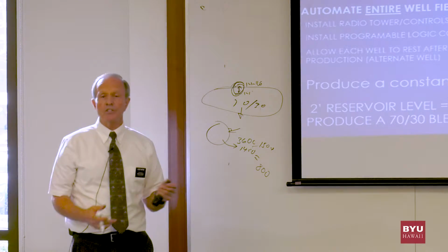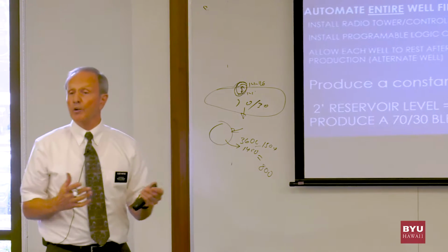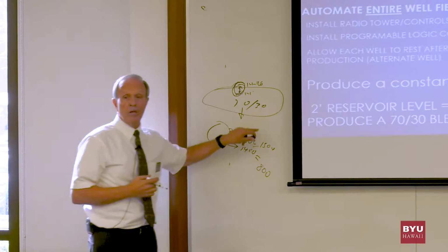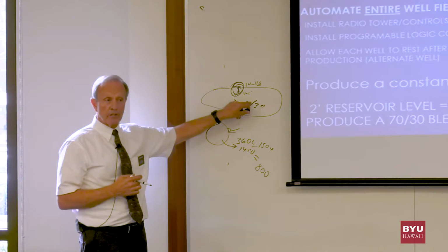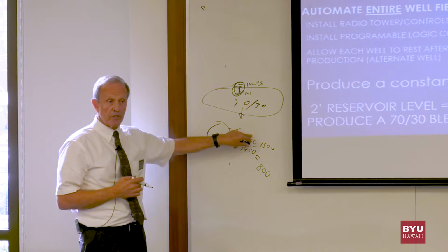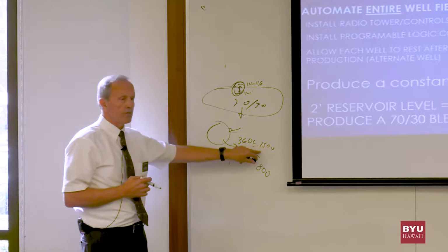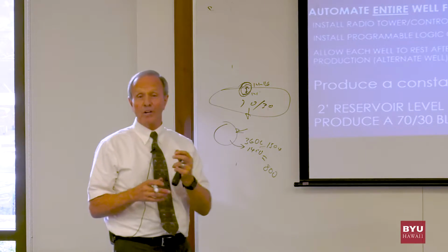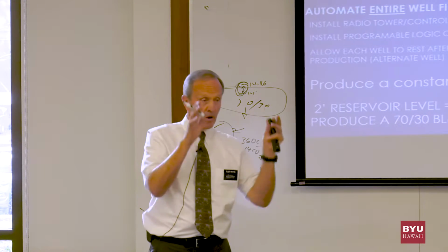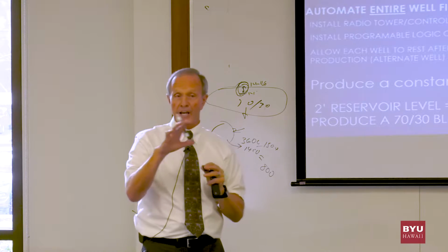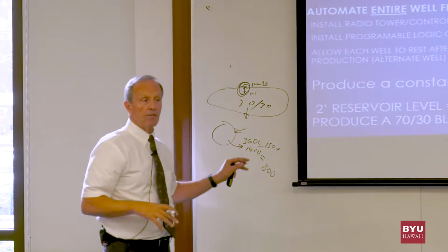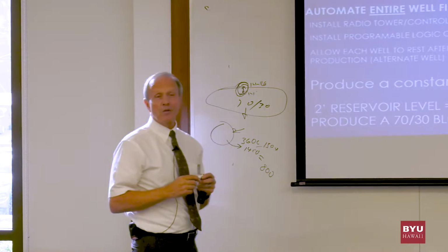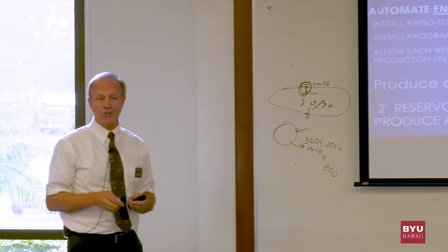When you kick it all the way up, it's going to produce 1,500 GPM. So what you have is these variable frequency drives on your pumps. That helped this scenario because now this well could turn this off a little bit more, or he could turn him on a little bit more. He could run it at 3,600, or he could run him down at 1,500, or whatever the case may be. So all this fantastic automation was all there. I'd get in there, I could look at my monitor, I knew exactly what the well fields were, I could see the levels. It was just unbelievable.